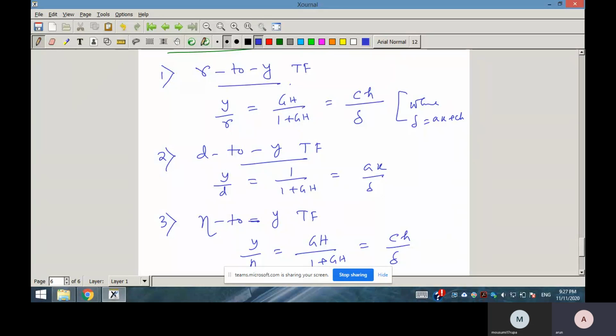Similarly, in pole placement you also do not know where the controller poles will get placed. Once you place delta, the controller pole and zero polynomials will automatically get placed. So you do not know. Because if the poles of the KS are close to the imaginary axis, then again there is amplification in disturbance to output, and the disturbance attenuation property will be poor.